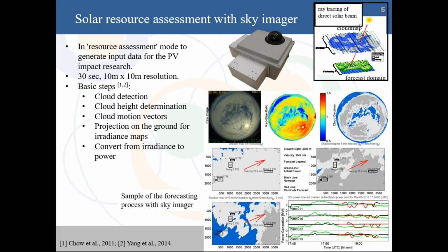And then we basically have to overlay these clouds onto the ground. So we see here a snapshot of about a 2.5 by 4 kilometer area of the ground, which could be a distribution feeder. We're now overlaying these clouds on this map at the same time as showing the solar power systems on that feeder. So with those systems you can forecast typically about 10 to 15 minutes ahead, depending on height and the cloud speed. So it's a fairly limited horizon that doesn't help much with most energy markets, but as we show in this example, actually it can help with the distribution system operation.